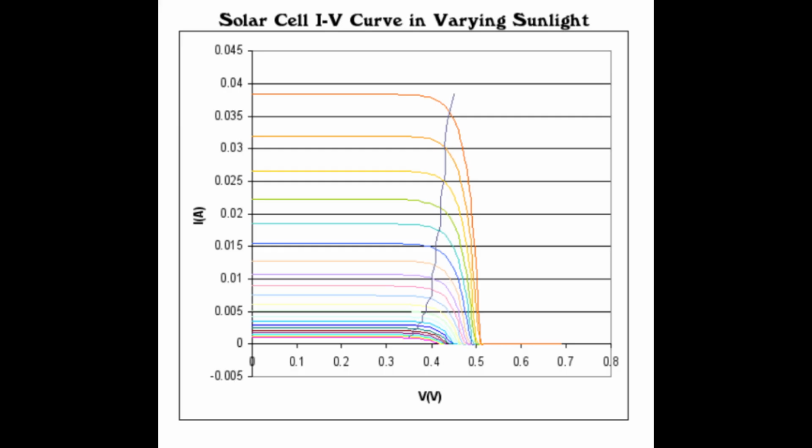For maximum power output, each solar panel in an array should be maintained at what is called its maximum power point, or MPP. This maximum power tracking voltage will only be the same if all panels wired together in an array of panels are of identical design, operating at the same temperature, and receiving identical illumination. This colorful graph shows the current versus voltage for a solar cell at different illumination levels. When the sun gets brighter, current goes up. The rising line intersecting the knees of each curve is the MPP.